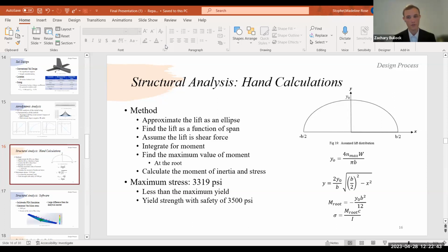And I'm unsure if it was either due to us using a value that was not conservative enough, or if it was due to us using a value provided for regular PLA as opposed to lightweight PLA, and a difference in material properties resulting in a reduced yield strength compared to what we predicted. Okay, cool. I just wanted to make sure you guys considered the anisotropy, which seems like you did.